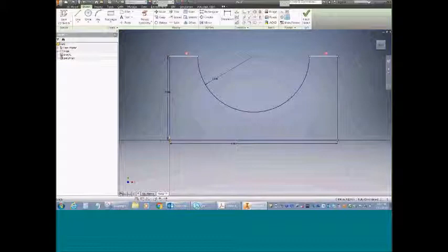I have my equal length constraint up here, and it highlights the geometry that the equal constraint is applied to, and here's my collinear constraint. You can see that when I was sketching this, because I sketched things really close to horizontal and vertical, those constraints were automatically applied. Here's a horizontal constraint. Here's a vertical constraint. A perpendicular constraint was applied to this one. I can set my preferences in the settings on what constraints I want it to primarily look for as I'm sketching.